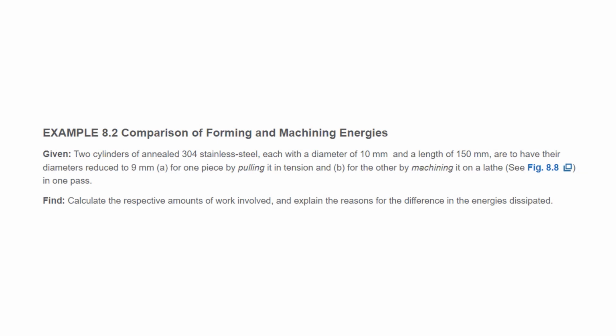So this gives us 33.5 times 10 to the 6 Newton meter per cubic meter. So Newton meter is the energy, cubic meter is the volume. And so this is the strain energy.